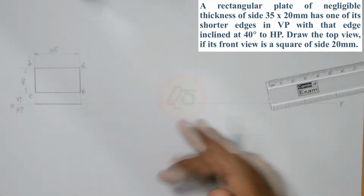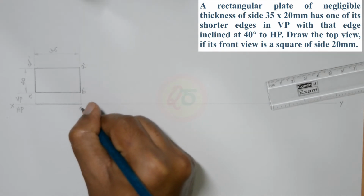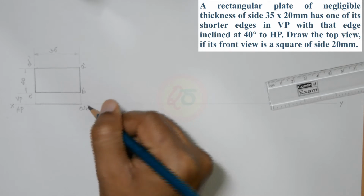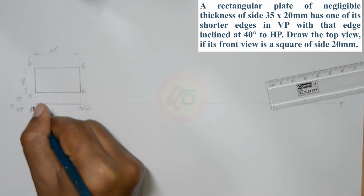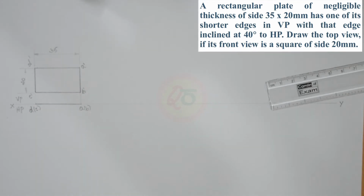Name them. From the top, A is visible, so A is written as it is. B is hidden, so B is written in brackets. Similarly, D is visible whereas C is hidden and it is written in brackets.